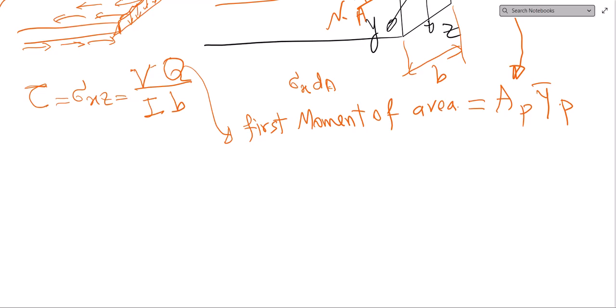Here we go with a bottom-up approach from displacement to stress and equilibrium. The variational approach takes it top-down, taking care of the strain energy and then minimizing it. I will explain that approach, which is called the variational asymptotic method.